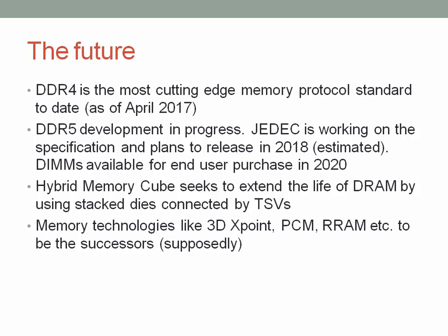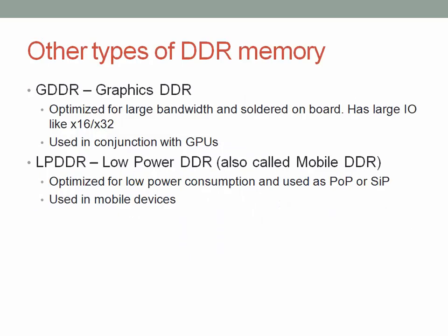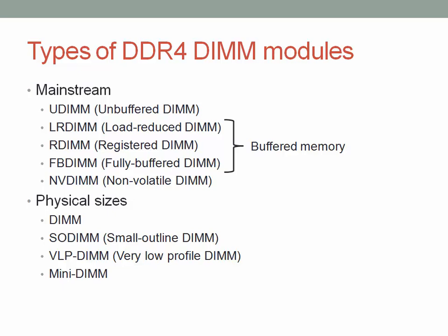So what kind of DIMM is used for DDR4? DDR4 uses all kinds of DIMMs. Go back to your listing of DIMMs. Does it use an unbuffered DIMM? Yes. DDR4 operates fast, so if you're going to operate fast, is it possible to use no buffering? I looked at the JEDEC reference design, and in the schematic the DRAM chips directly connect to the card edge connector.